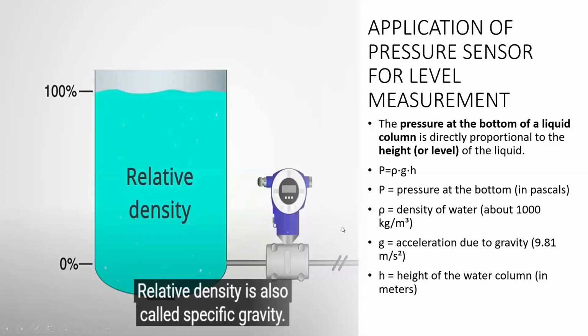Like I said earlier, there are things that can affect these, like the density and the type of liquid you are going to use. For example, if it is going to be caustic or if it is going to be oil, this needs to be known. Then foam or agitation may also affect the sensor reading. Put this in your mind. So you have to think about how you will mitigate this, maybe by filtering excess foam or thereabouts.